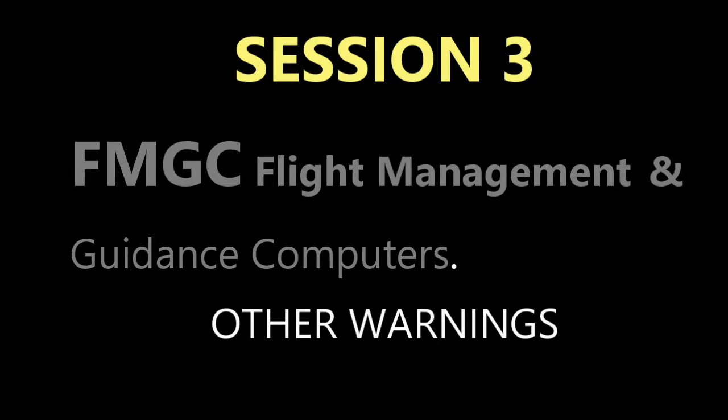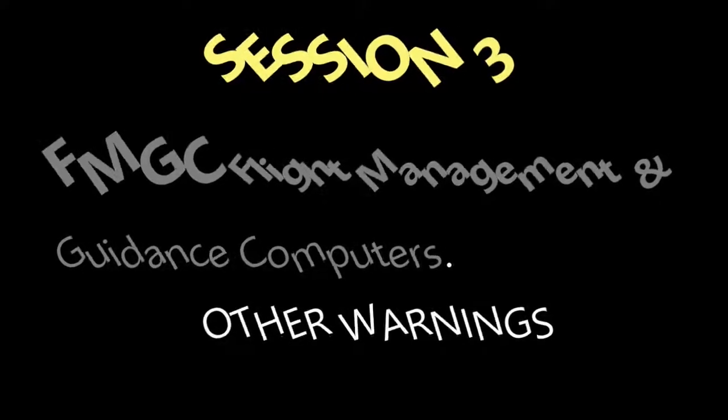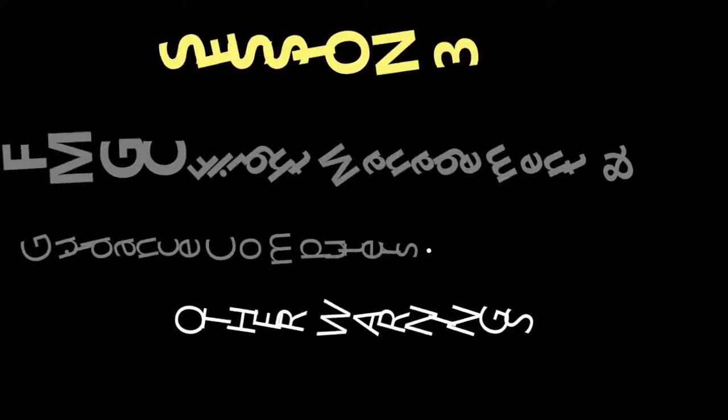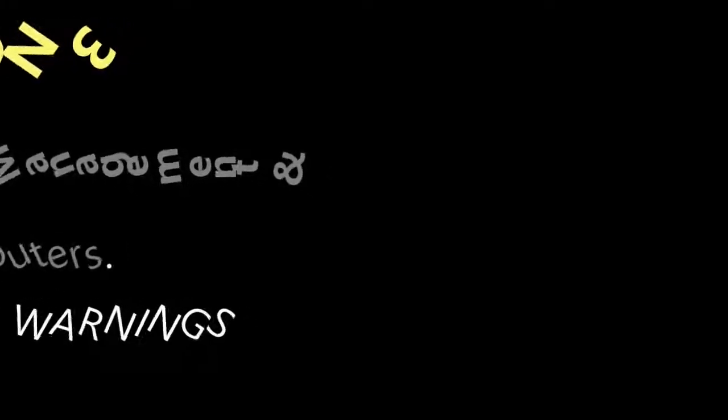So here, if you have the loss of the auto thrust, there's going to be a warning. And there are 2 cases of this, just like in some other ones. One is that you have a loss due to an action on an instinctive disconnect push button, or you have thrust levers set to idle that's performed above 50 feet. So with those conditions, that's the first case where you have a loss of auto thrust, and then you're going to have a warning. The warning is going to be temporary with this first one. So the amber master caution light is going to come on, but it's not going to stay on. After so many seconds, it'll cut off. And same thing with the auto thrust off message. That's going to be amber, but after a while, it's just going to go off. And then of course you have another one where it's not due to that action of an instinctive disconnect push button. So it's everything else.